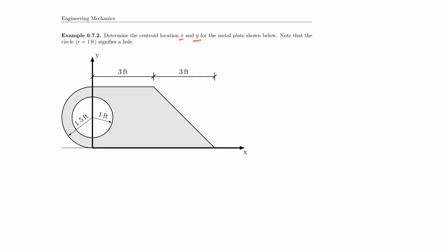So before I continue to talk about that, let me give you the answer to this problem. X bar in this problem actually happens to be 2.11 feet, and Y bar happens to be 1.34 feet. And now what you need to be careful about: the circle has to be subtracted, and then